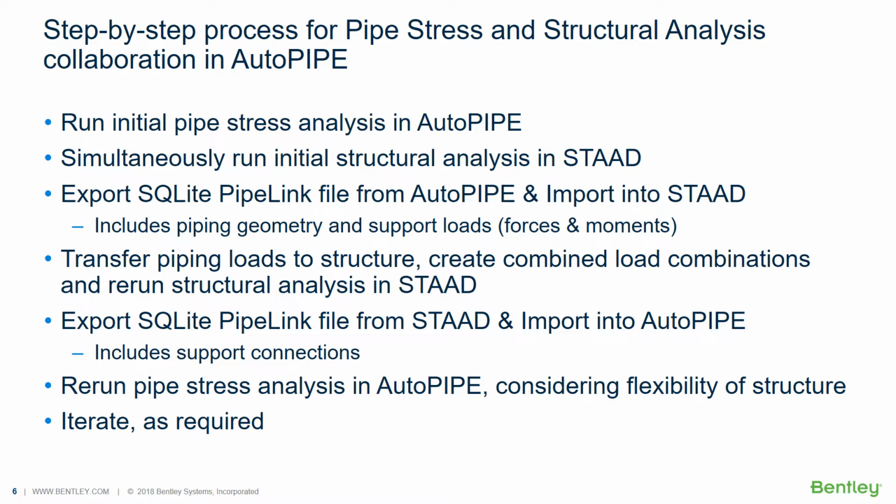So the next thing we can do is export our SQLite PipeLink file from AutoPIPE, and import that SQLite PipeLink file into STAAD. This export to import includes the piping geometry, and it includes the support loads, so the support forces and moments for all of the load cases that are being considered on the piping side.